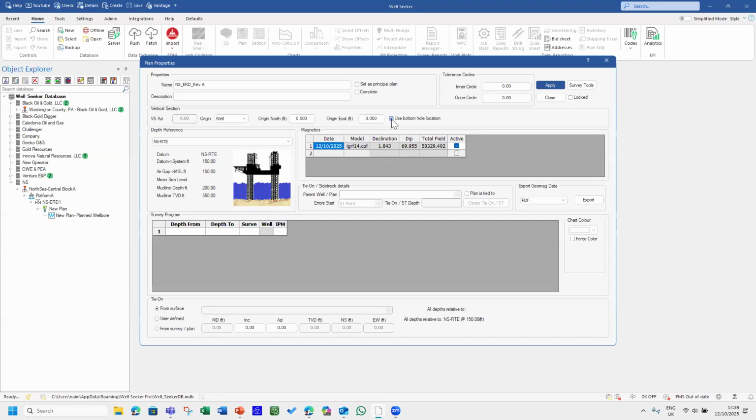This is telling you the curtain, the vertical section. If you have been involved with any drilling, you know what vertical section is, but some people don't know. A vertical section is actually the view from the side. If you're looking at an ERD well from one angle, it will look like a vertical well. Same well looks like an almost vertical well. But if you see it properly from the side, at one angle, it will look like a very long well, a proper ERD well. So this vertical section, if you get it wrong, then your well will not look right in the section view.